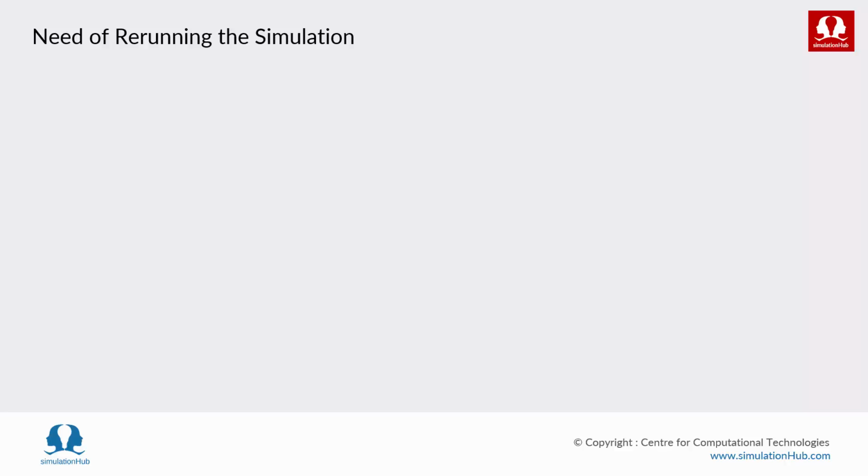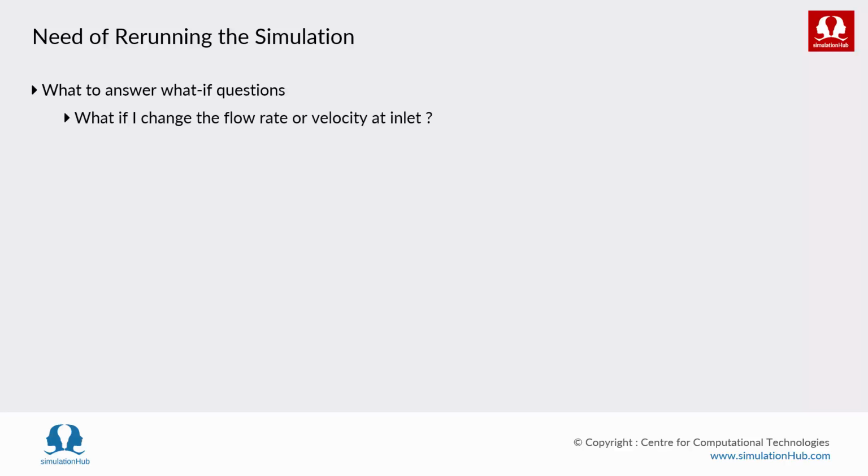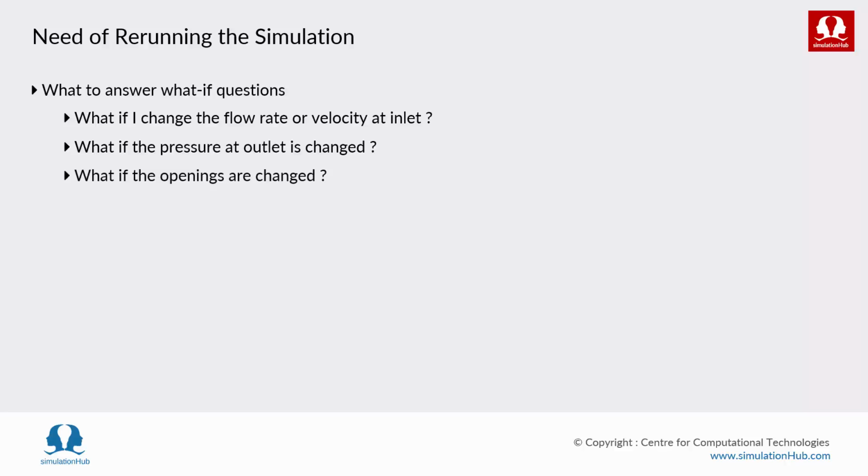Now, what is the need of rerunning the simulation? The main need of rerunning the simulation is to answer what if questions. For example, let's say I want to change the flow rate or velocity at the inlet. Let's say I want to change the pressure at the outlet and see how exactly flow behaves. And I want to see if the openings are changed. For example, if there are multiple inlets, if I close one of the inlets, what would happen? So there are many what if questions that a designer needs to answer. So rerunning the simulation will help the designer to evaluate the performance under different sets of boundary conditions.